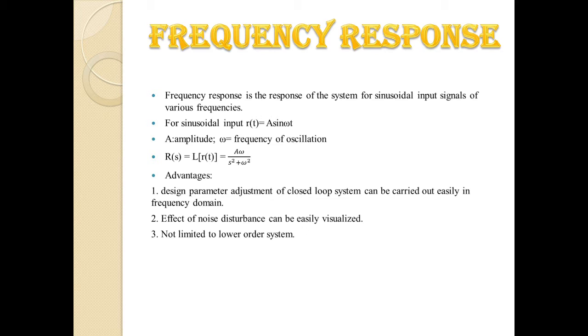If r(t) in the time domain is A sin omega t, then in the frequency domain, after taking the Laplace transform of r(t), we get R(s), which is equal to A omega by s square plus omega square.